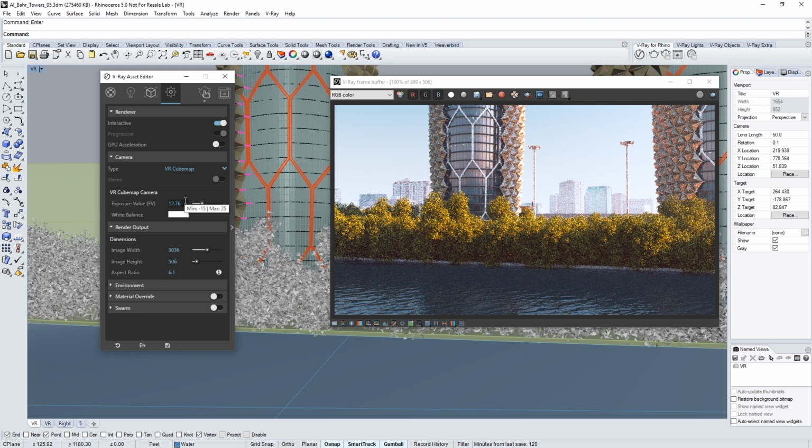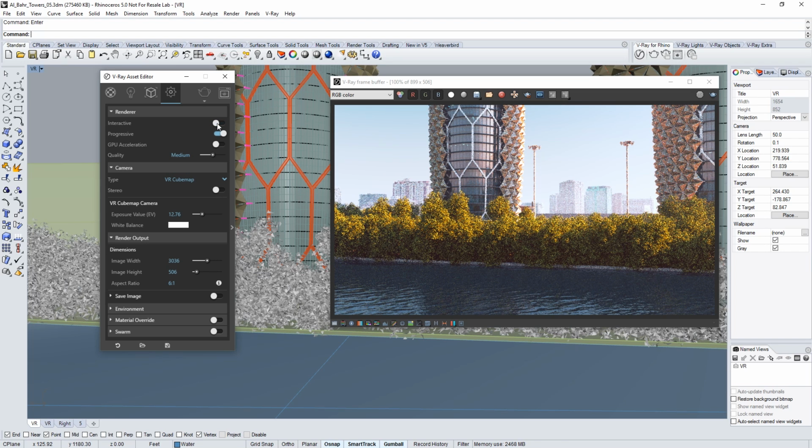Both of them have pros and cons regarding how easy it is to see the whole picture, pixel optimization, seams, distortion and filtering. Here, enabling the stereoscopic effect, VRay will render a VR image per eye, left and right, and these two images are shifted with a human-sized distance, the distance between your eyes, to get an even more 3D virtual reality experience.